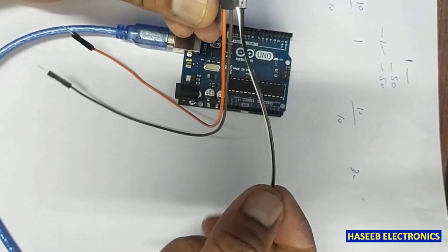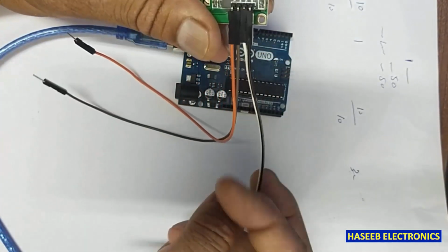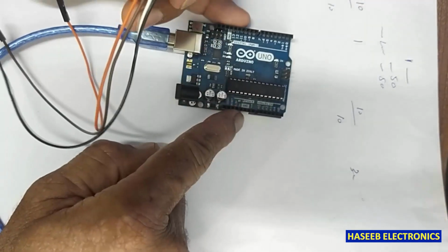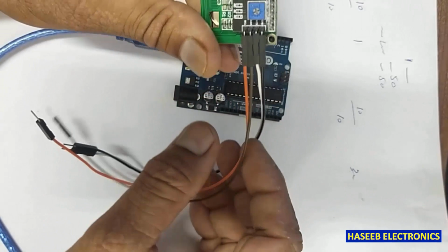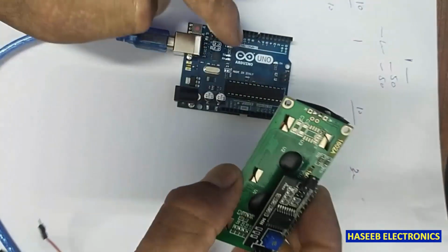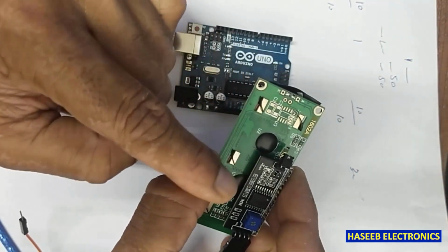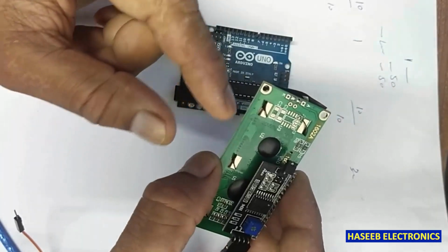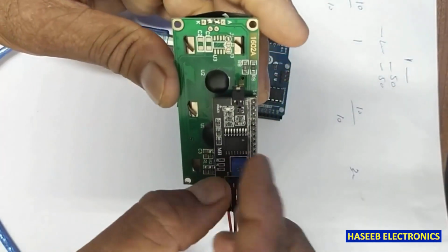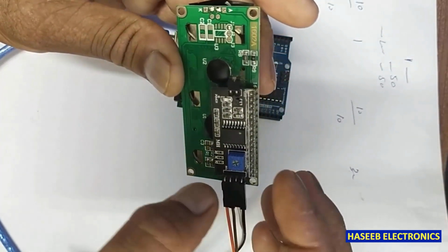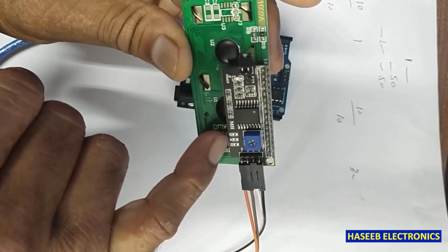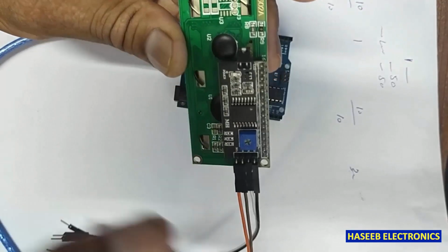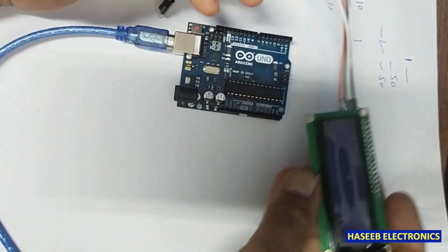It is using positive and negative voltage, VCC and ground, which we take from this Arduino board, and here it is just clock and data. So this talker can talk with many devices in parallel, because every device has its own assigned listen address. When these jumpers are open, it will use address 27.